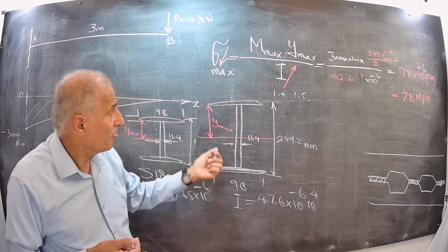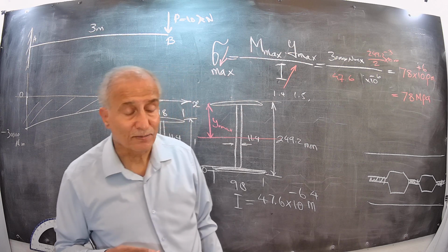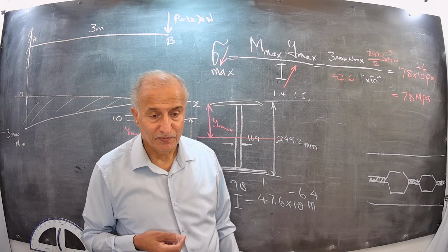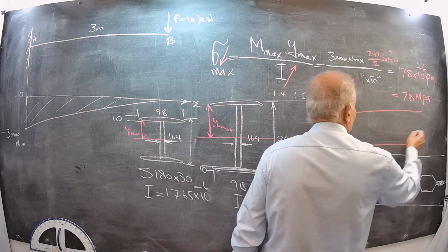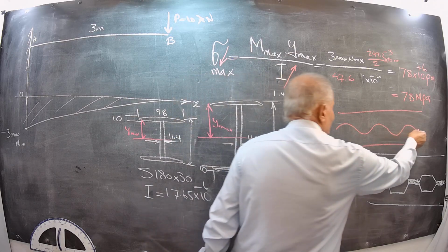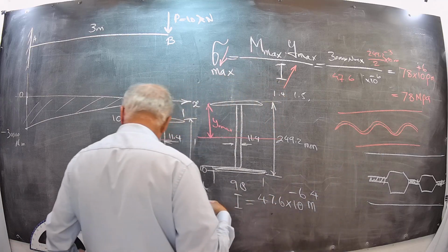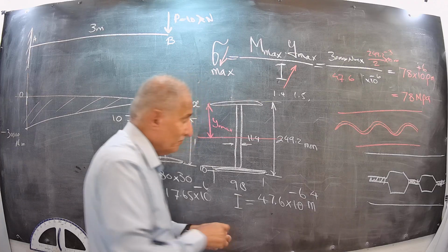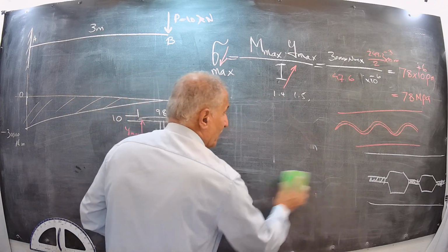This is called opening, when the opening is hexagonal, it is called a castellated beam. And if the opening is circular, you cut it like that, then you move, and then you make a beam, separate them again, shift one opening back or forth, and then your beam is like that.